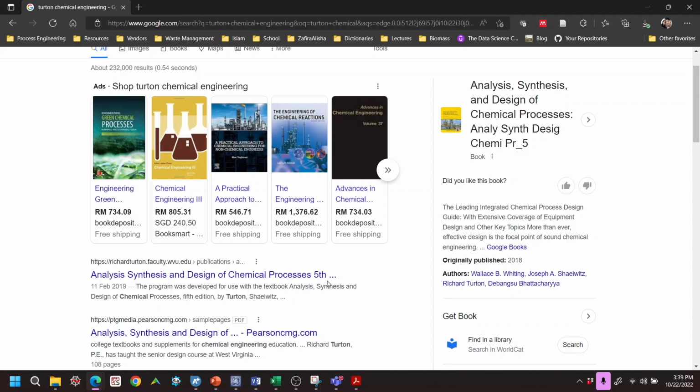So don't model the reactor as a conversion, because then you already know what the answer is. But for the sake of effort, if you model the reactor based on the kinetics and it has recycles in it, it will need more effort to converge, and when you run case studies, sometimes it doesn't converge. So you have to do some tweaking, which requires a different set of skills, which we're not going to elaborate here.